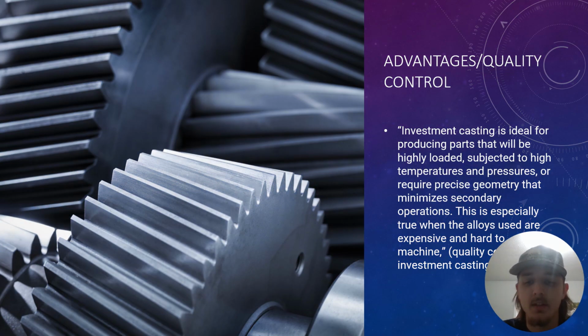So there are many advantages to using investment casting. Investment casting is ideal for producing parts that will be highly loaded. They'll be subjected to high temperatures and pressures or require precise geometry that minimizes secondary operations. This is especially true when the alloys used are expensive and hard to machine.